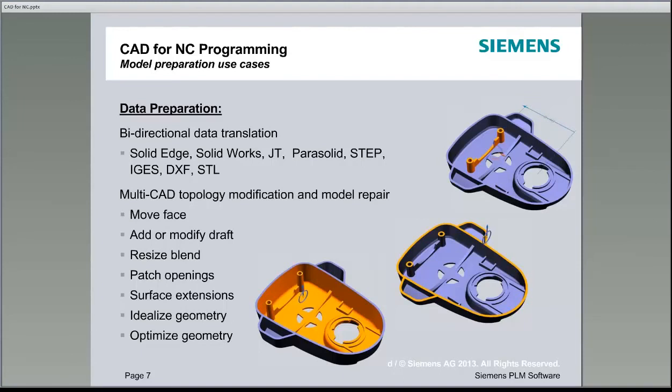As you see in this little model here, we can find the post and the rib. We can dimension to that and dimensionally drive that particular feature. Not only can we just drag it on the screen and turn things on and off, we can literally redimension that or reparameterize it back into an intelligent solid model meant for a manufacturing process.